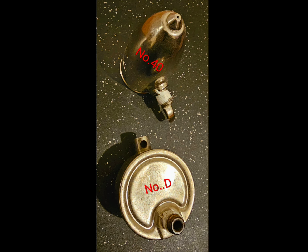And what I did, as a matter of fact, is if I wanted to know if one of these vents was still working, I can test them on a radiator that was set up in my apartment. And now I'm running this system at 7.5 to 8 psi. That's the cutout. And if the vent stayed open and didn't close, and that boiler came in, cycled in and out, in and out, in and out, in and out, and that vent stayed open, guess what? I knew that vent wasn't working.